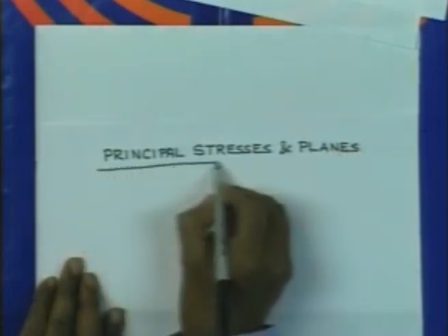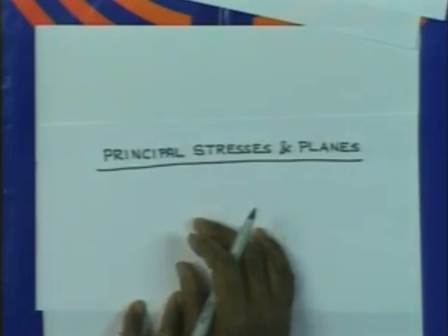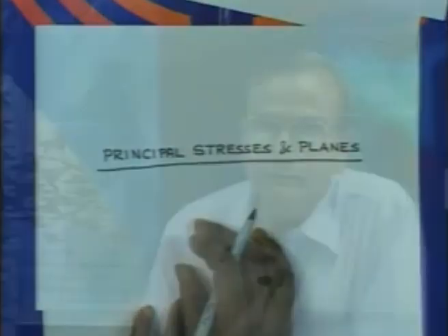So determination of principal stresses and principal planes. Do you remember what is principal stress? These are the stresses which act on planes where there is no shear stress. So we would like to now consider determination of such stresses in 3 dimensions.